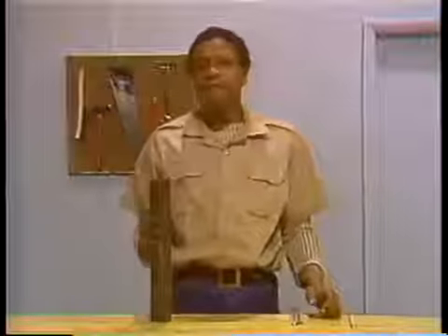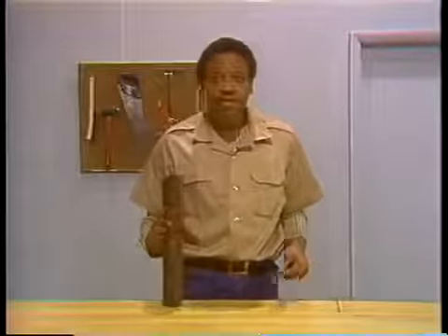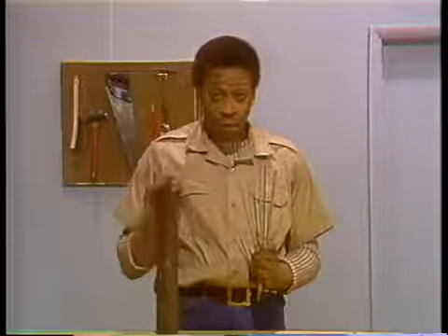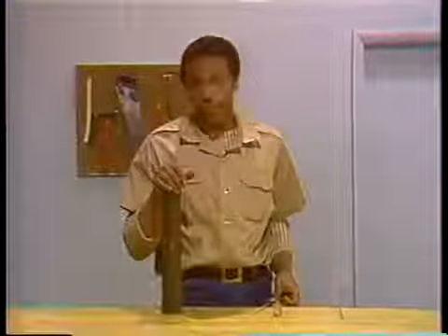The type of metal that the tube to be repaired is made of and the type of weld rod used for the job are both important considerations. There are a lot of different kinds of weld rod available, and there are a variety of metals used in boiler tubes. The type of tube metal and the type of weld rod must be compatible. If the wrong kind of rod is used, the weld made with it is very likely to fail. For this reason, the foreman or an experienced welder usually chooses the type of welding rod.